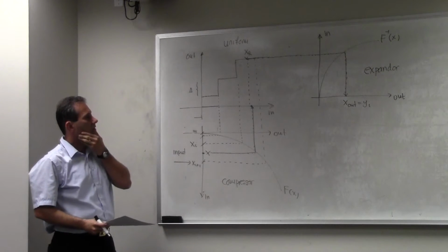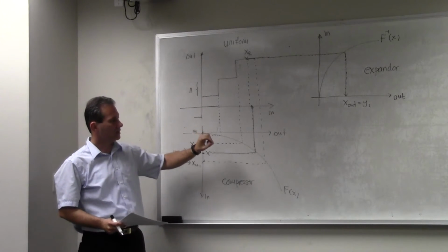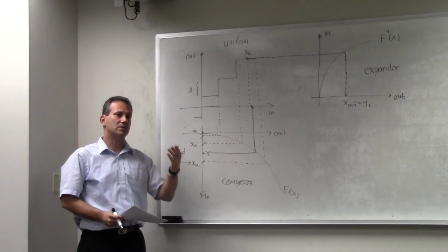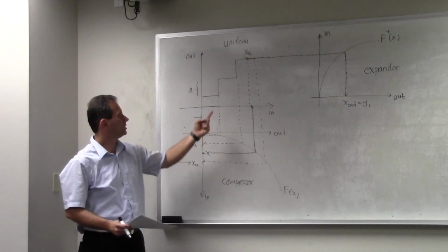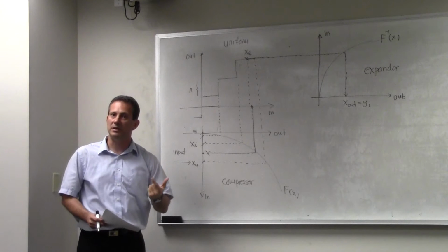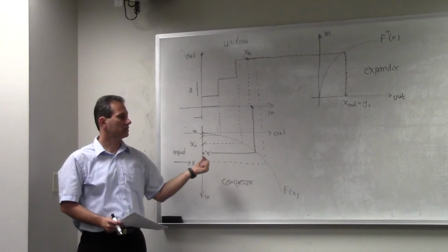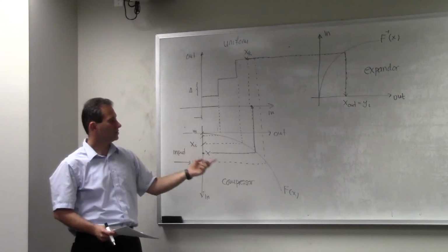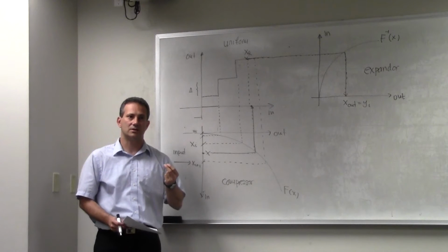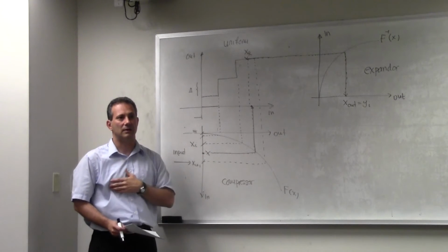Now, what is our goal here today? Our goal is to describe this mathematically, and to derive the expression for signal to quantization noise ratio that is now going to be a function of principally three things. Your delta, which is the quantization step of your uniform quantizer; the PDF of your signal, which we discovered last time it has to be a function of; and then the third, this f of x. We're going to try to select f of x in such a manner to minimize, to eliminate, the effect of the PDF of the signal.